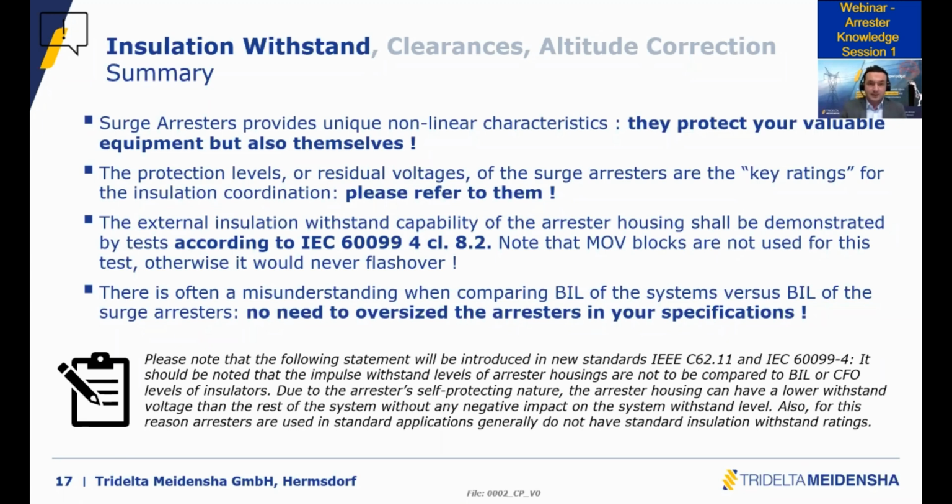Then the external insulation withstand capability of the arrester should be demonstrated according to the surge arrester standards in paragraph 8.2. And as I explained before, it's very important to understand the concept that when we go to the test lab to perform this insulation withstand test, the arresters are filled with insulating material. We are not using surge arresters with active part, otherwise the surge arrester will never flash over.